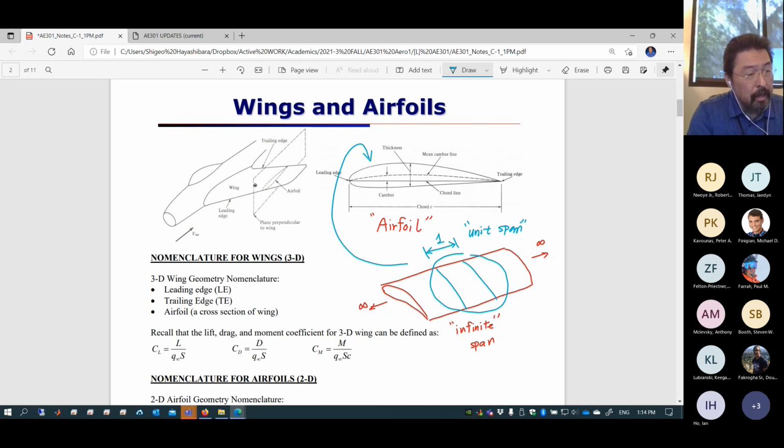In other words, later on in project 3B, you're going to pick up the software and try to design your airplane wing. An airplane wing is made up of a choice of cross-section at each unit span. If you choose a single shape, you can create the wing, of course, because your cross-section is all the same. It's sometimes called a chocolate bar wing, a Hershey bar wing, and the only design parameter you have will be aspect ratio.